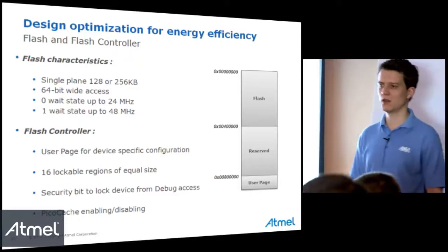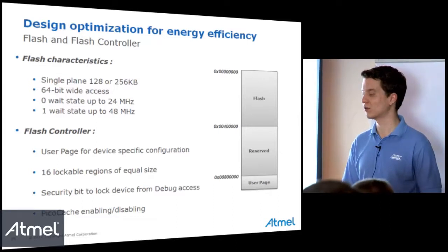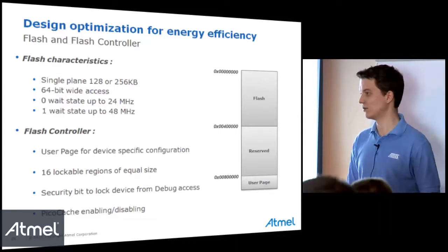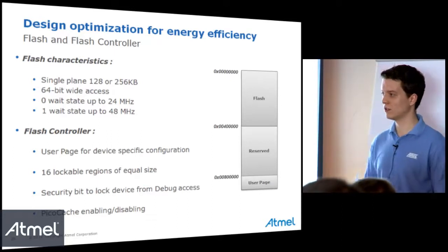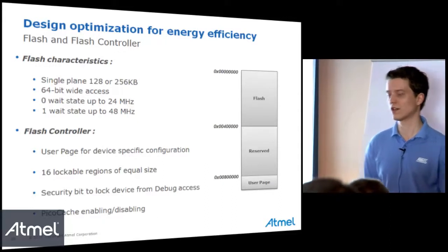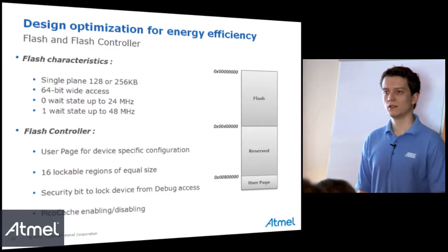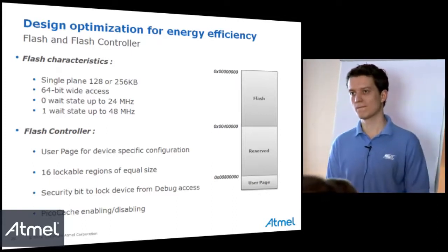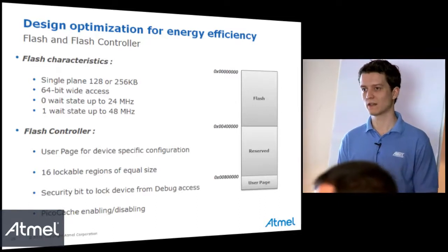This is why I don't understand that we have in JTAG something that allows resetting this security bit, because JTAG and SWD should be disabled. It's not directly disabled. The way to access it is different from standard JTAG access. Okay, perfect. So it doesn't disable the debug port, it just locks the flash down so that the debugger can't see it. Yes, exactly.